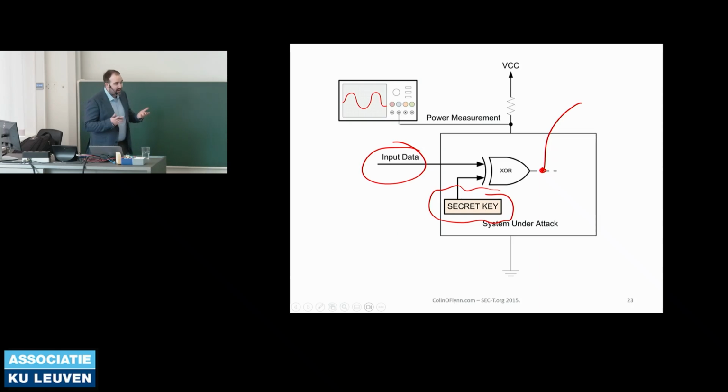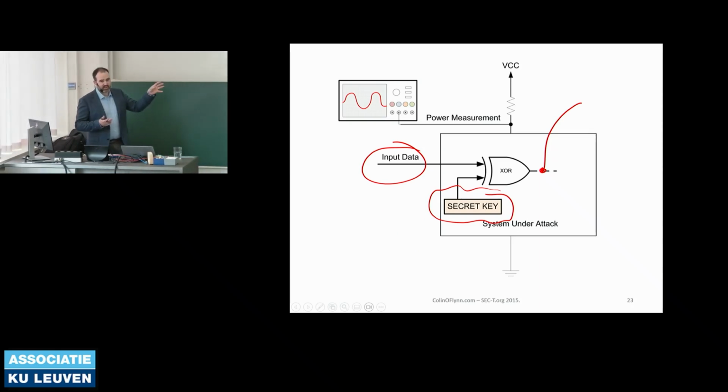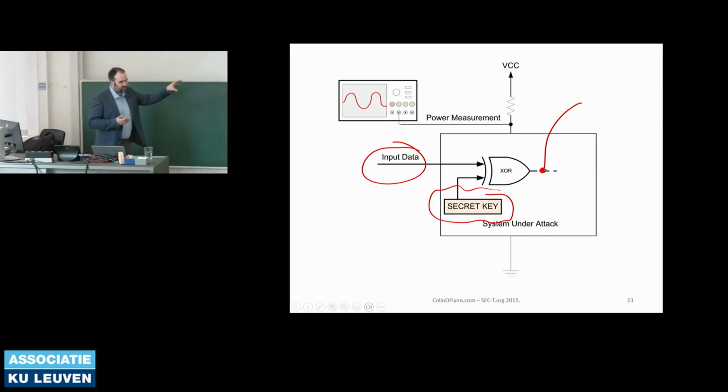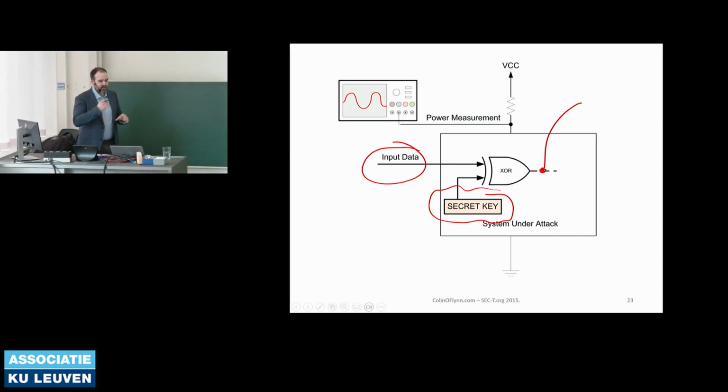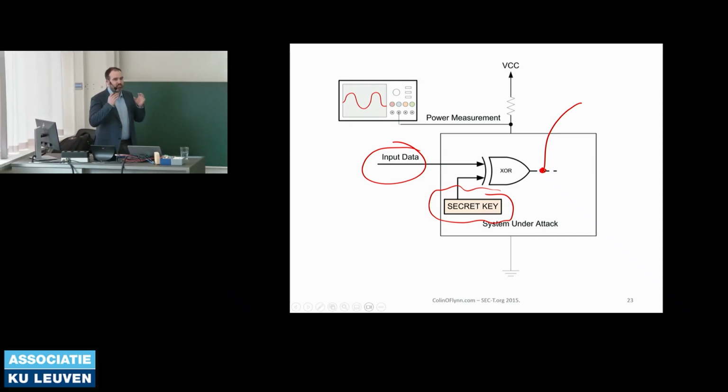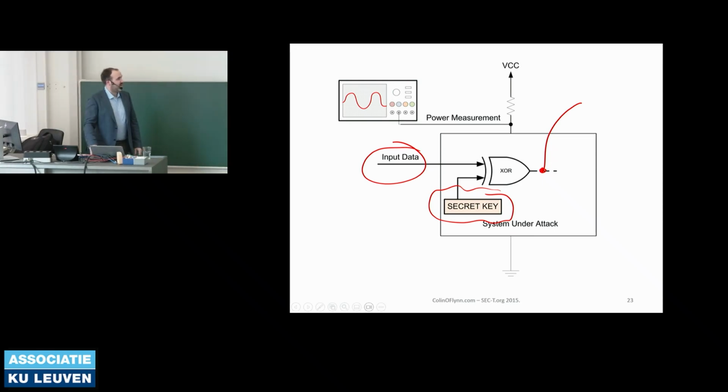If the device didn't have an S-box, you can still do it with just the XOR. You can use this, for example, if you're looking at an AES in counter mode or something where you didn't have the same ability to look after the S-box because the input data was fixed. So you can choose other points is the quick answer, but it's just a convenience of that exact attack.